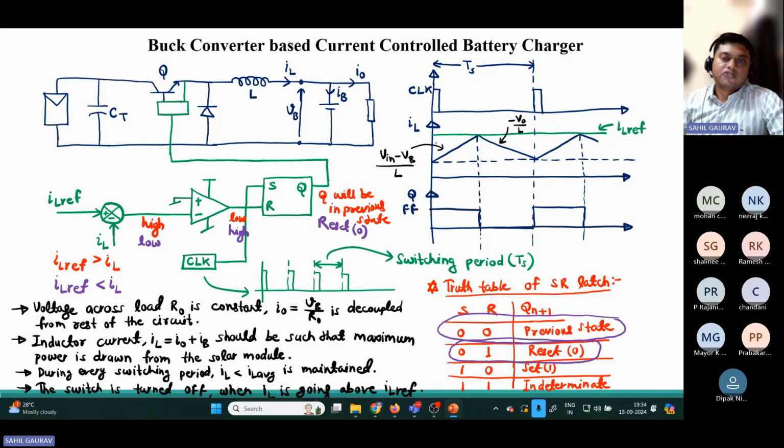So in this logic, this converter is operating. If you see here, this inductor gets charged when this IL difference is greater than IL, and once this inductor current wants to increase beyond this IL difference, then it resets this flip flop, and it provides the pulse, it turns off the switch, so our inductor gets discharged.